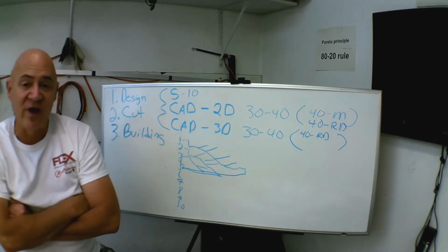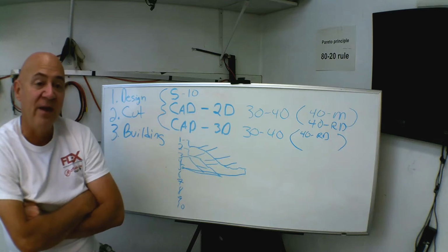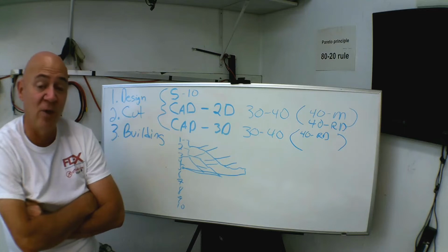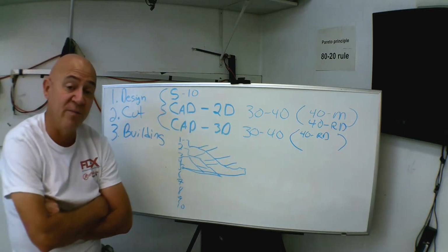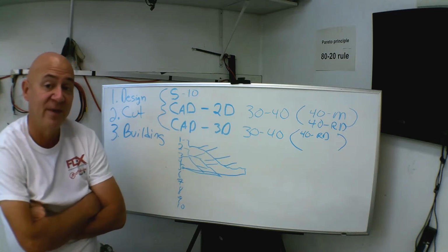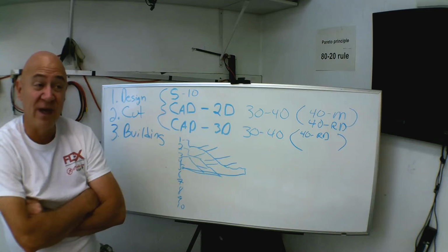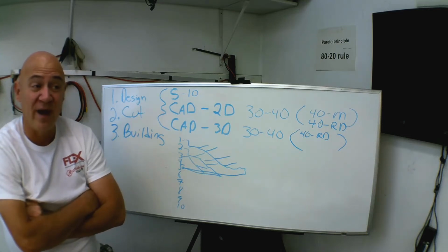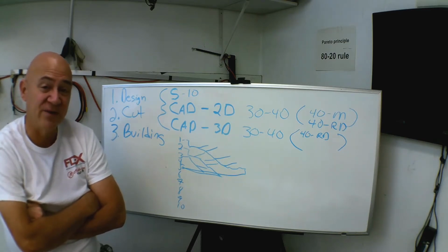But what happened was when I found out they made a Hacker motor big enough to fly that airplane, well, then I put it in there, but I had to cut the nose off and extend it 8 inches to get the CG right, because that electric motor weighed a lot less than that 150cc twin cylinder internal combustion, that 3W150 I had. So that airplane, from the moment I started it to the moment I test flew it, was 6.5 years.